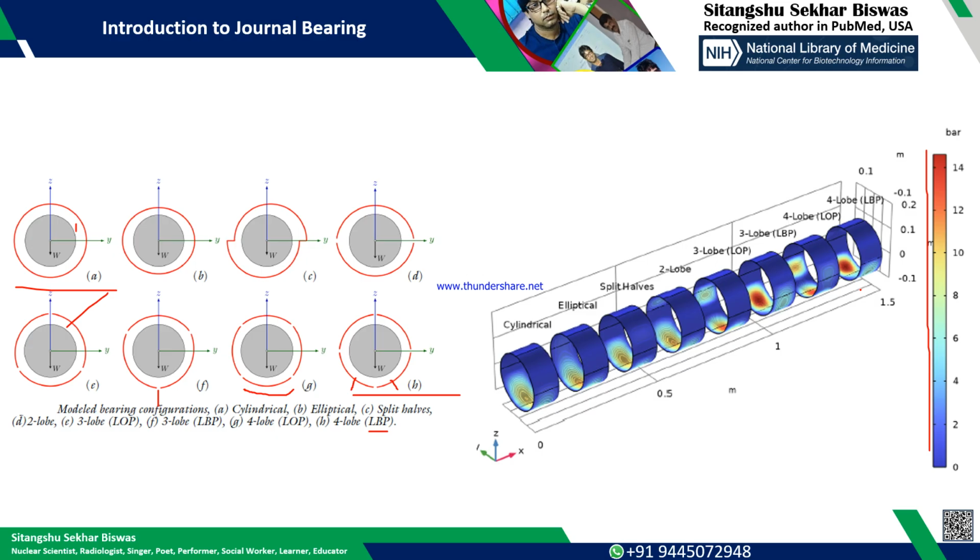And you might have seen, interestingly, the coupling between the prime mover or the motor and the pump is not a rigid coupling, it's a flexible coupling, because the motor is not designed to handle that full inertia. Along with the motor having one inertia, along with that the pump inertia, that load is there.